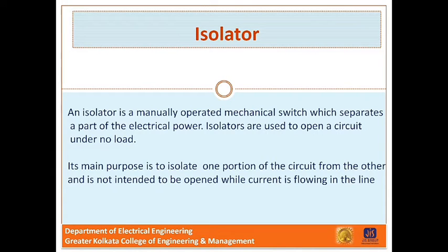Now a circuit breaker always trips the circuit, but the open contacts of the breaker cannot be seen physically from outside of the breaker. And that is why it is recommended not to touch any electrical circuit just by switching off the circuit breaker. So for better safety, there must be some arrangement so that one can see the open condition of the section of the circuit before touching it.